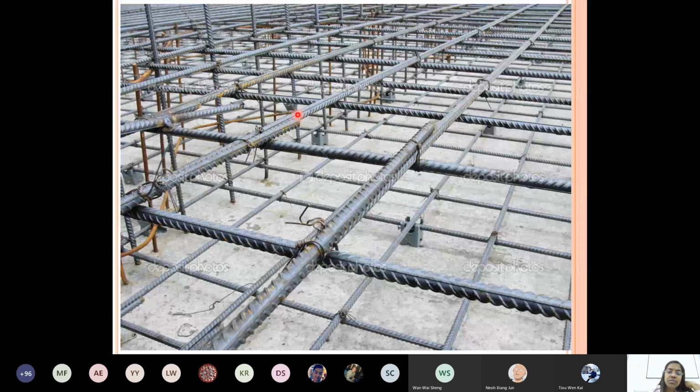All fixing. See the bars are tightly closed and there are overlaps also. You can see some overlaps. You should avoid such overlaps because it may be over designing or a problem for your concreting. I mean, not much. You have to know how much it is.